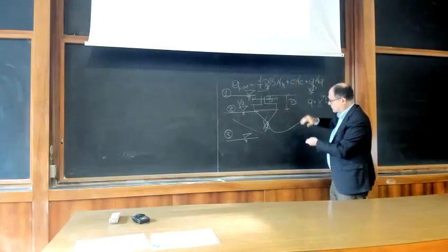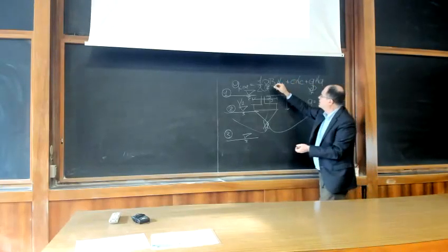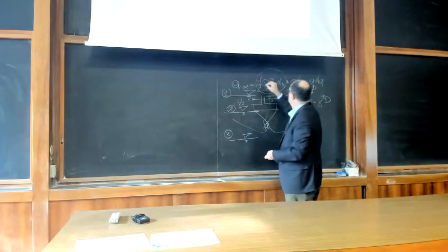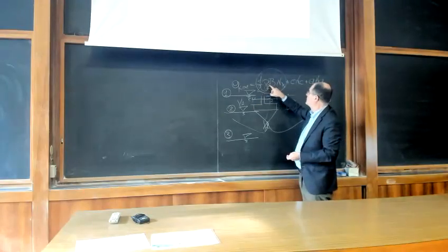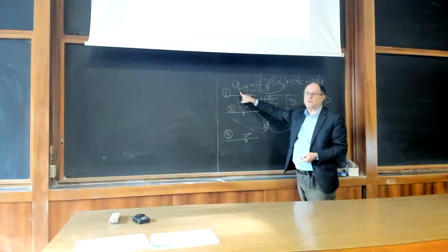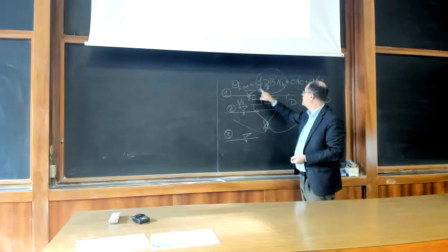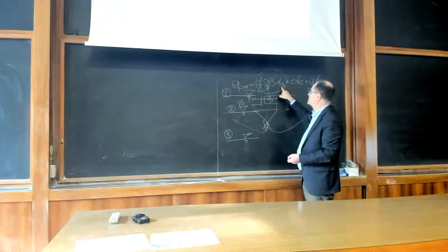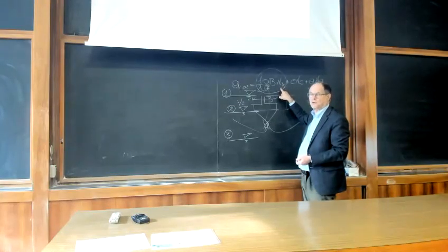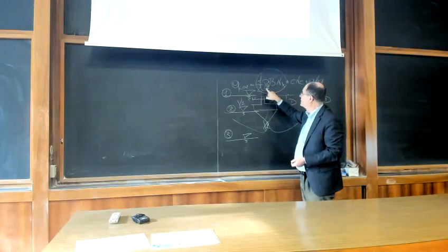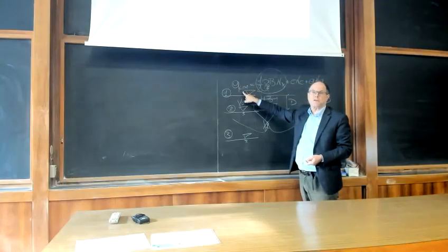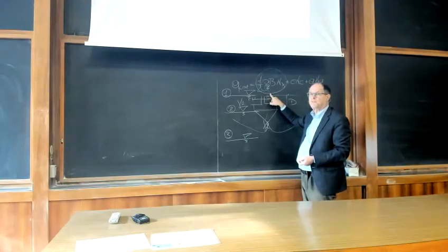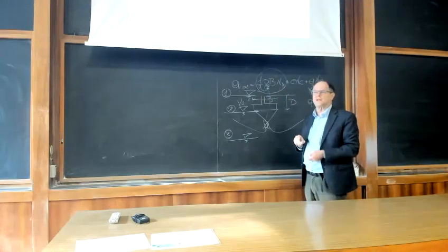If you have only this term, and you put gamma dash or gamma saturated, you end up with a limit pressure which is twice as much, depending only on gamma, and irrespective of everything we have just said about N gamma, which is a function of phi. Also, this can affect your bearing capacity. So it is very important that you select the correct gamma value,